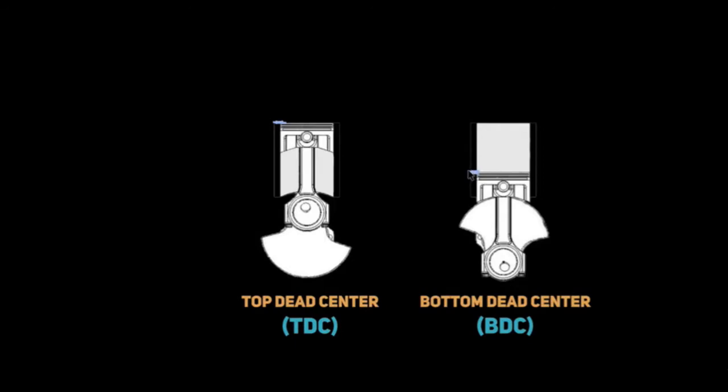From this, we can now see a piston stroke. This is the distance the piston slides up or down from top dead center to bottom dead center. So one 180-degree rotation equates to half a turn for the crankshaft. So if we start right here at top dead center, the crankshaft would move all the way down here. And then vice versa for bottom dead center. It would start at the bottom on its way to the top.